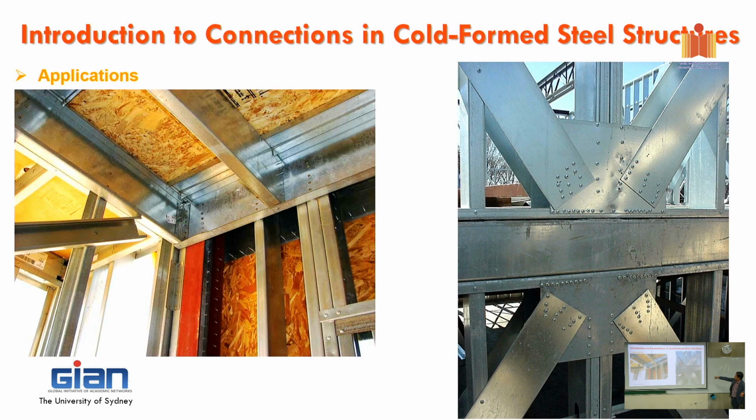All right, so this is one example of a bracing system in a mid-rise building for a cold-formed steel structure. What are the cross sections of the bracings? In here, I'm not 100% sure inside, but I think this is a strip. This is the plate, yeah. You can see the plate, the strip. They screw here as well, they screw into the member as well. So this is just the plate for the strip, and they just screw it. That's why they have two, because it's always going to be in tension. That's how it works.